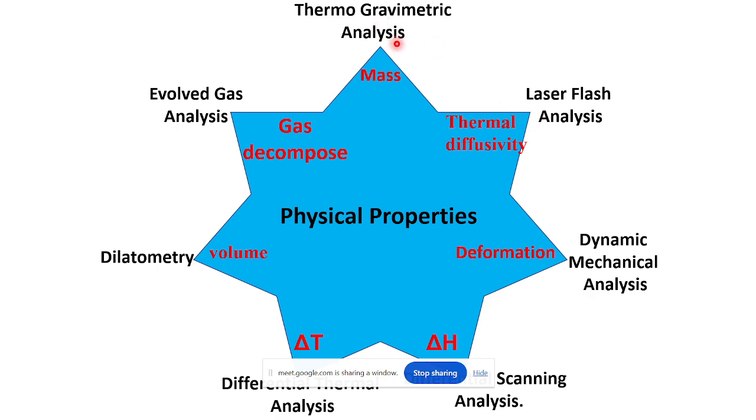So this is thermogravimetric analysis, that is TGA. Last week we also discussed it a little bit. So what we study here, you are scanning temperature and you are measuring the weight loss. If anybody has experienced TGA, please you may ask questions. So what we plot in the thermogram, we plot weight loss versus temperature.